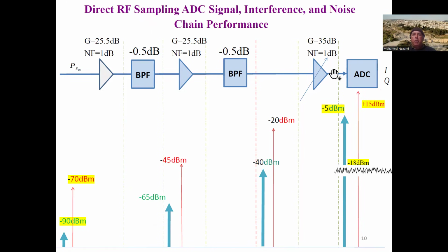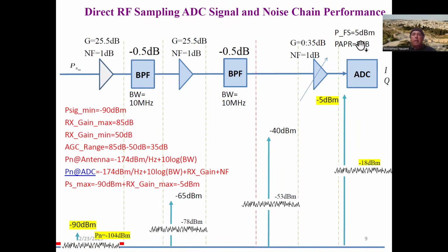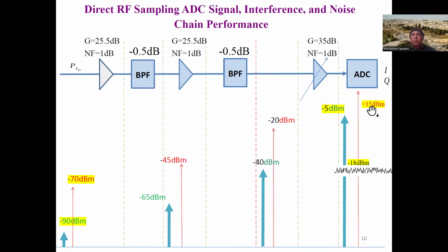And this 80 dB, of course, the full scale, above which we're going to clip, is really plus 5 dBm. And you can see here it's plus 15 dBm. So right away you can see that this ADC will be in saturation. And that's assuming that these active amplifiers in here did not already clip and saturate, producing harmonics and tremendous noise level raise. Okay, so right away you can see that there is an issue in here.